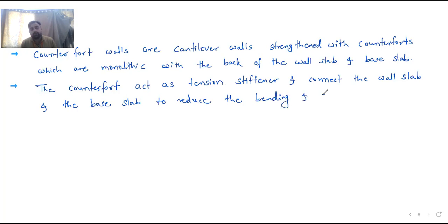So the counterforts that are provided act as tension stiffeners between the wall slab and base slab, due to which the bending and shear stresses are getting reduced.